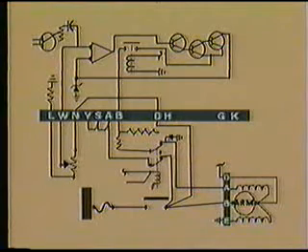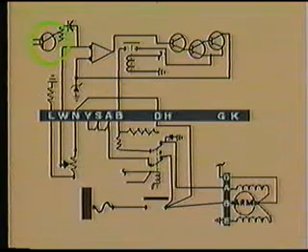The next major consideration in the generator circuit is regulation. Here are the internal components of the control panel involved in regulating the generator output. We'll start with the upper left corner with a component that resembles a transistor. This is an oscillator circuit which generates a constant stream of signal pulses.